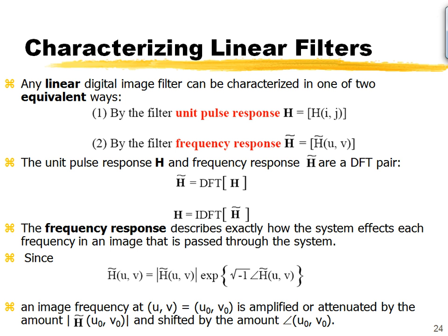So oftentimes we end up designing filters in the Fourier domain, taking its inverse Fourier transforms and applying them as linear convolutions, not necessarily applying the filtering operation in Fourier domain. Okay. Now, the frequency response of any filter that we design is nothing but the filter's DFT. Right?